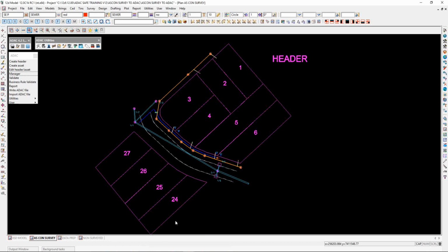Those ways can be like a data input as a DWG, where any real information other than the name is really lacking on that data. We also find that even the names change from drawing to drawing, so you can't be consistent in what you're getting per input. And then there's the data pickup by the as-constructed surveyor, who uses codes and names and often attributes that define the asset. So the type of data you receive plays a large role in the processing of that data.